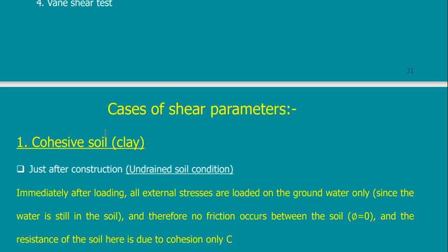What did you say? It is something related to water, but it is the dissipation of the water. Water is not something bad. Water is something good in the soil. But the presence of water and it being not able to leave the soil upon loading is a problem. So here, clay is a problem. Why? Because the permeability of clay is very, very low. So when it includes water and I put a load, water will carry the load.